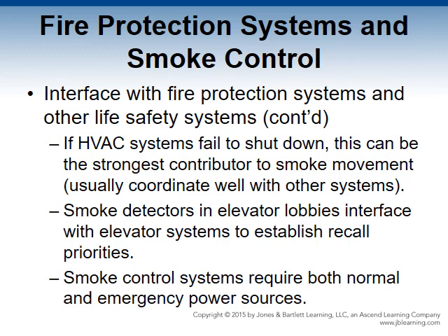If the HVAC system and its components respond correctly, the only path left for the smoke is the stairways or elevator hoistways, which are often pressurized to prevent penetration by smoke.